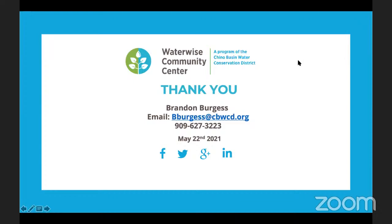Probably not. One of the easiest ways to do a gray water system, in my opinion, is called laundry to landscape. You can buy conversion kits where there's already a pump that pumps out your clothes washer, converting that into an irrigation system, depending on how frequently you wash your clothes. That might supplement a little bit, but I wouldn't run that into a drip irrigation system because of clogging.